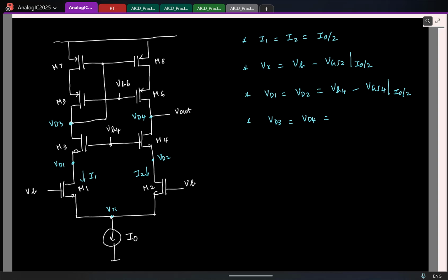So if the transistor is in saturation and the current is fixed, what should get fixed? VGS. For the PMOS it is VSG, right? So if I mark this as VSG, now help me write this voltage now, gate voltage. This is the supply VDD. So it is going to be the source voltage here, which is the supply VDD, minus the source to gate voltage of M7 or M8.